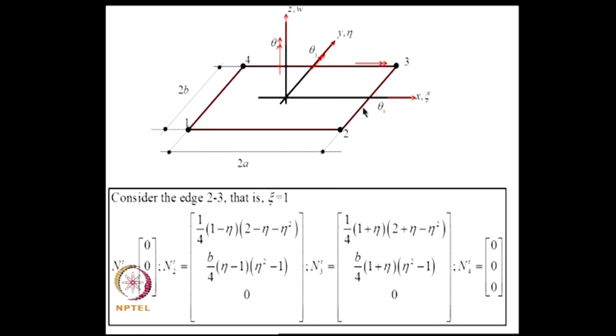Similarly, the point on this edge considered as a member of the neighboring element which I am going to add will depend on the other 2 nodes which are outside this. Consequently, there will be a lack of continuity of the field variable across the edge.